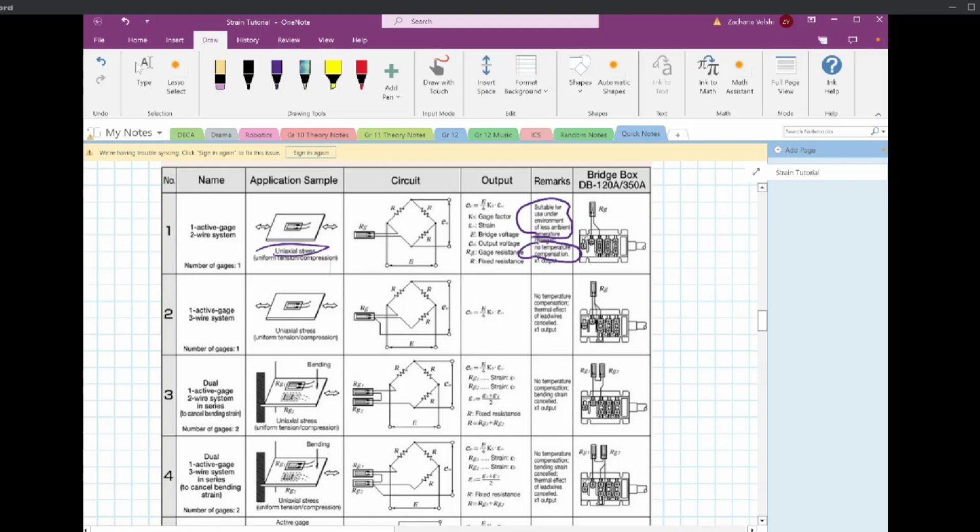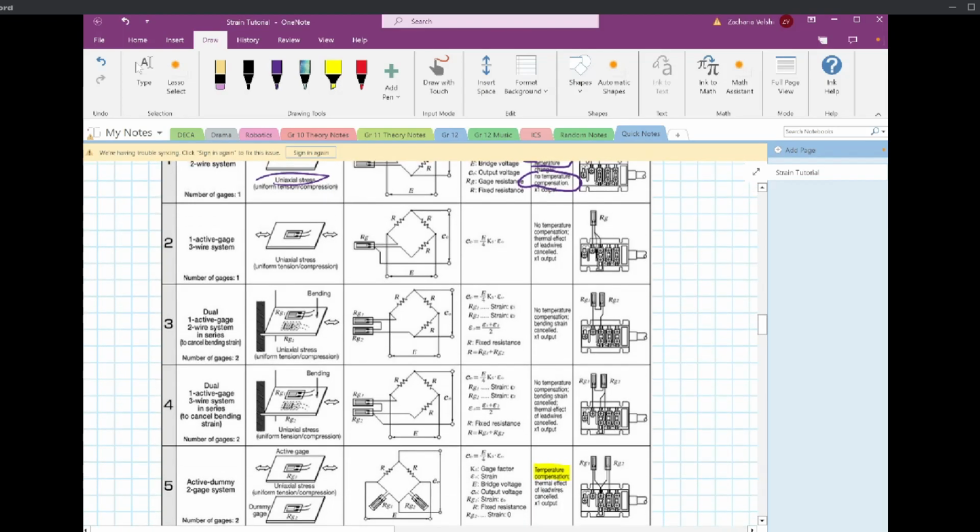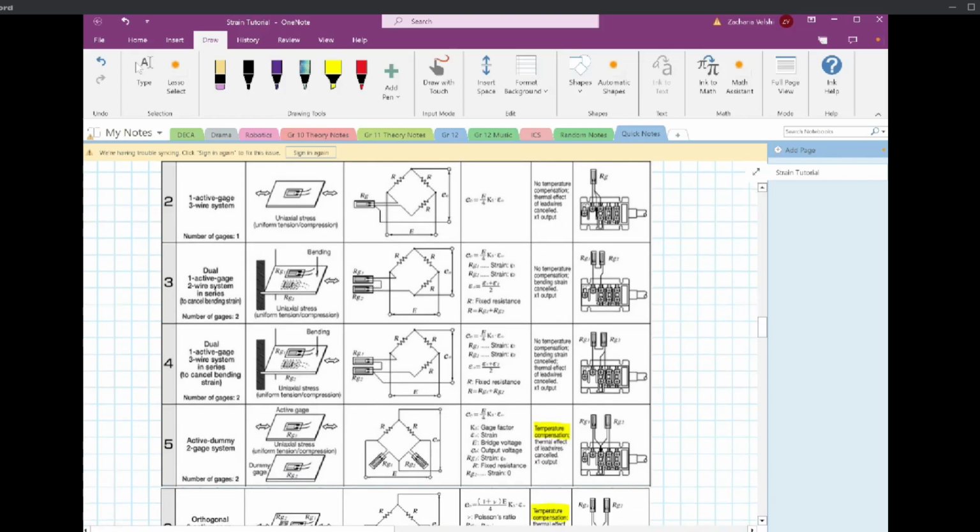Even like me and Schmitty, who have been applying a lot, I've been applying for like the last 2 years, and he put on like 16 in the last couple weeks for his wheel force transducer. Even he's found that it's like a 50% chance if you actually get it right or you don't. Even if you line everything up and you get it right, the chance that it'll actually stay adhered and actually work the way you expect is not great. But I'll get more into application in a little bit.